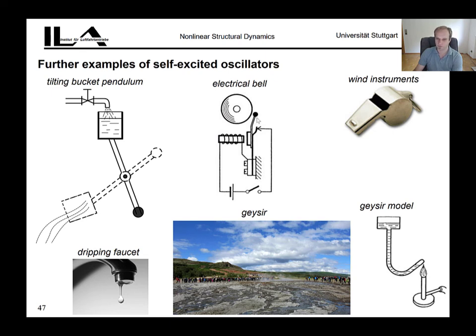And during this, because this is connected to this and then moves to the left, the circuit opens, and because it opens, the electrodynamic force goes to 0, and because this bell has some inertia, it goes back to its initial position, closing again the circuit, and then the process repeats.